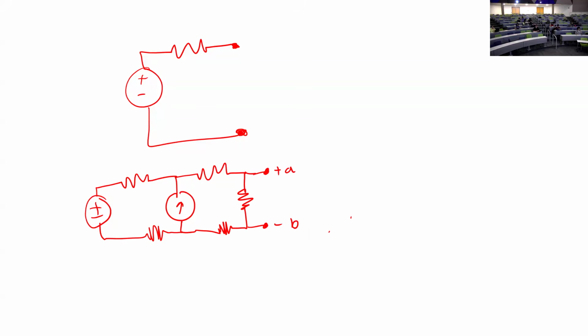Because the only thing I'm actually going to see at those points is a voltage and some sort of load or resistance. So a more typical application of this is if I plug in my phone to a charger, right? That charger can act as maybe a resistor that delivers power. But what does it see when it looks inside my phone? You'll see something that looks like some simpler version of a circuit that sums up all the complicated stuff happening in a way that is easier to analyze and understand. So whatever this complicated first step is, we want to get it simple. All right. So this is our Thevenin equivalent.